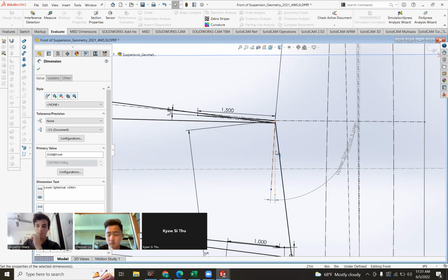That's also pretty complicated, but basically the misalignment angle in the spherical bearing can be physically intuited as the angle between the wafer and that top plane of the knuckle, because the bolt goes down and mates to the knuckle on the bottom. The nut is what defines the angle of the bolt. So that is the top face of the knuckle, but the outer rim of the bearing is seated in the wafer. So the wafer to the top of the knuckle is the misalignment angle.